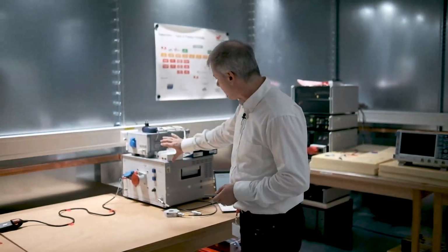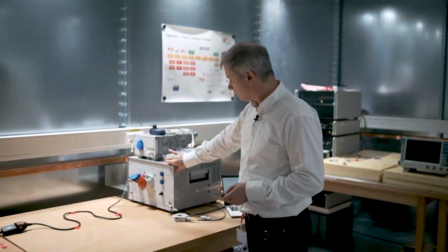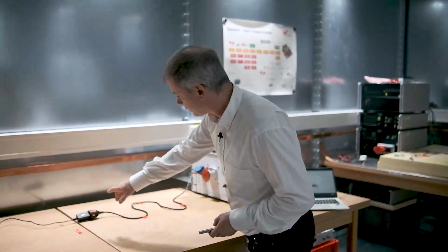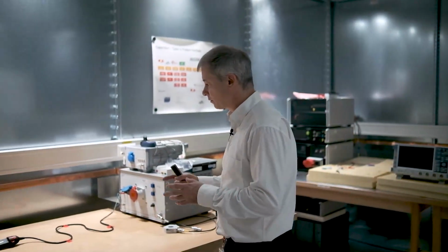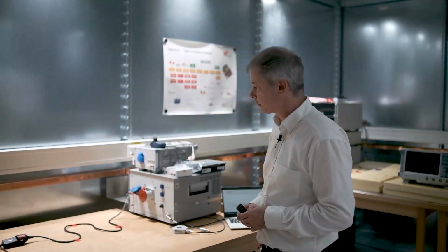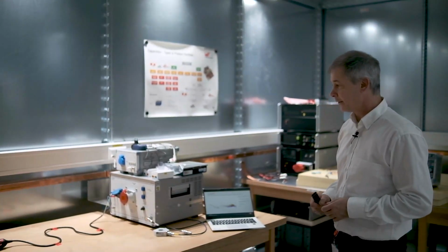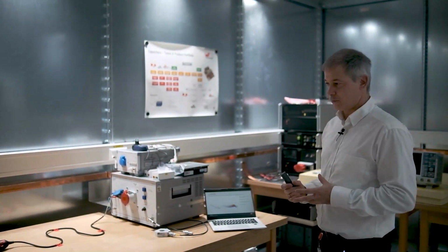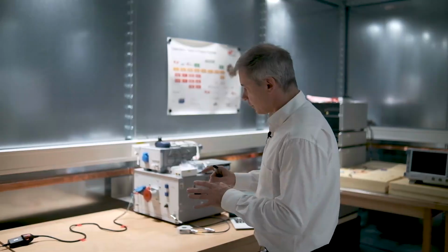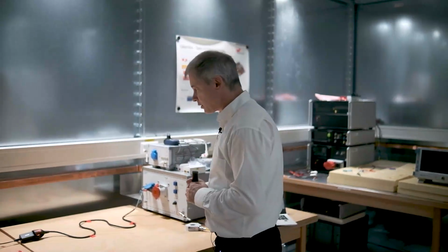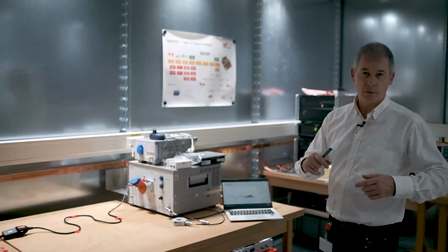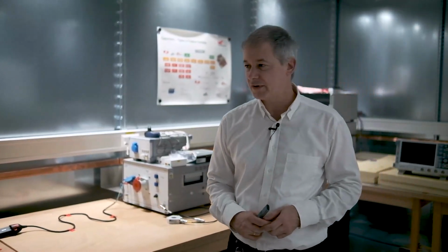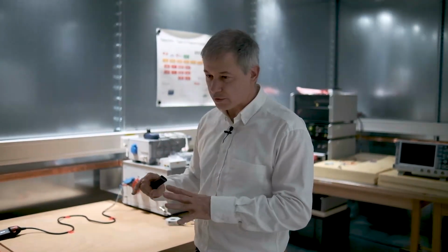And we have here the AN for AC, and connect the DC supply or the inverter to DC together with the Qi2 transmitter to have a complete system. And this is what we will measure outside the chamber in the measurement tool. And now I will go outside and show you the results of the empty measurement without any load on the transmitter.